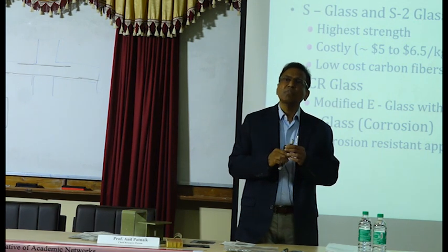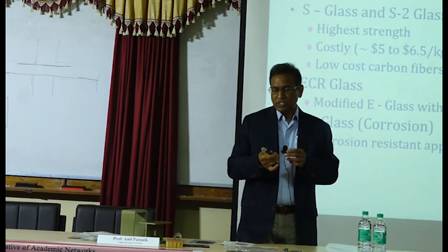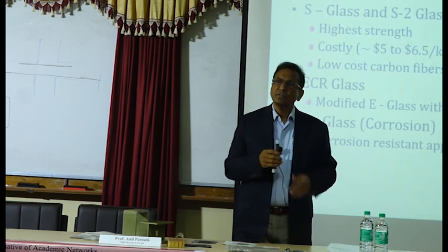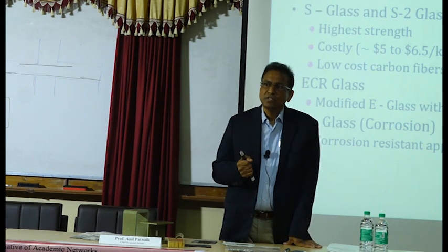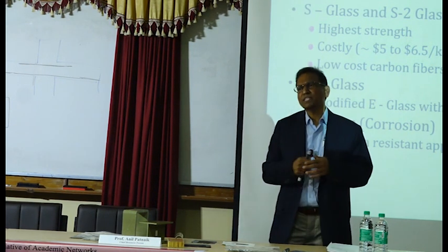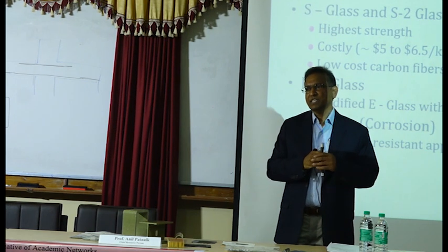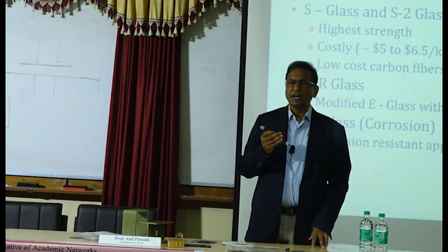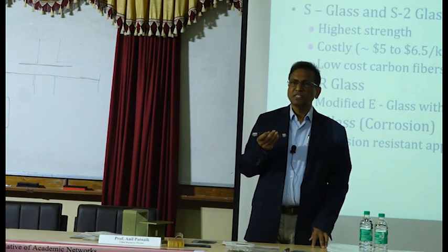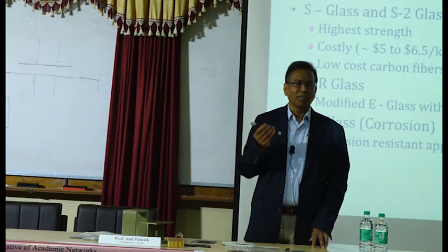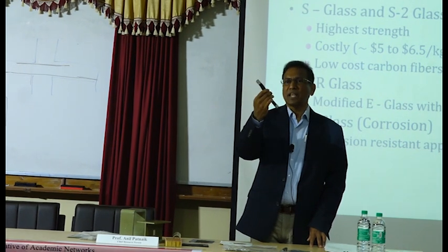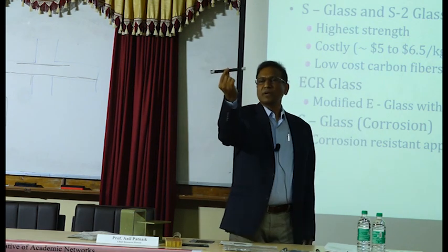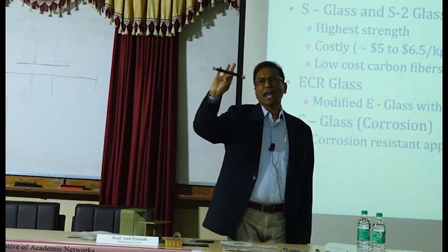So what's the normal grade for your strands here? 1700. 1700 is about 250 KSI. So this is slightly stronger than that, 270, which is no big deal. And here we have carbon fiber cable strand, same.